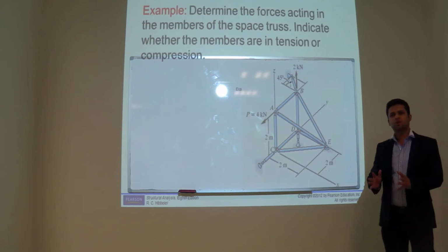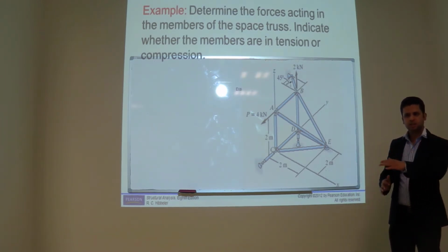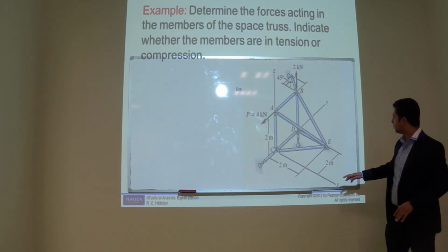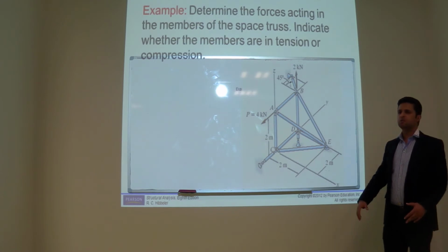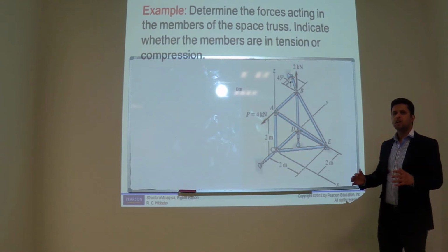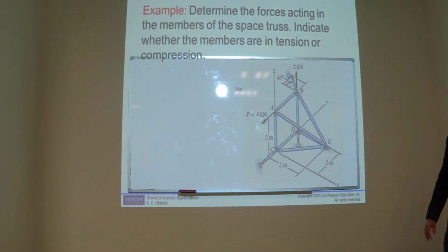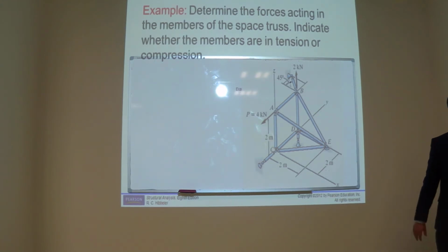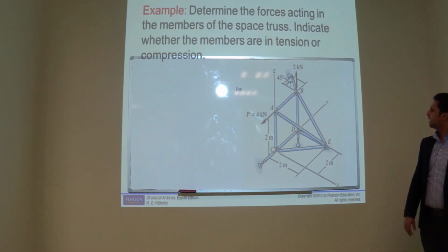And then you have to resolve each force. When you apply sigma fx, you have to consider all the forces and the reactions as well. Then you proceed to apply sigma fy and sigma fz, and if you make any mistake, your answer can be wrong. So it's very hard. Same is the case if you have to determine the force in member AE and you say that you will cut a section.